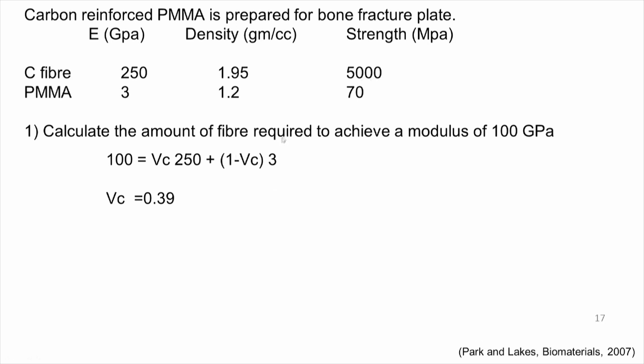Understand? Okay. So, we can multiply by the corresponding volume fractions to get the overall modulus, or if you want to calculate the maximum strength it can take, we can multiply their volume fraction to these strengths and then add them up.